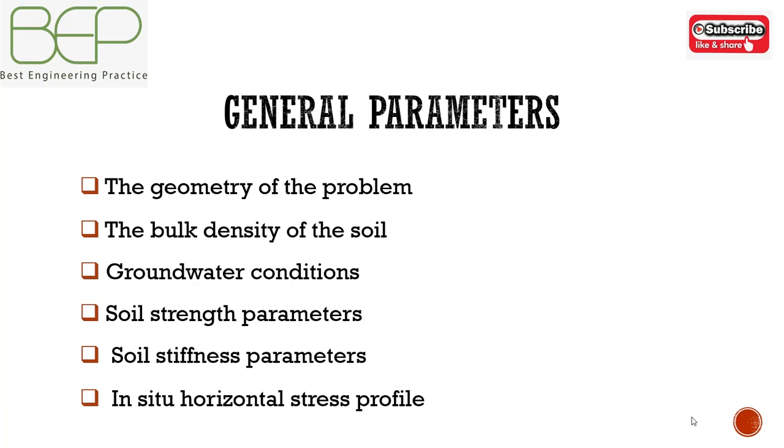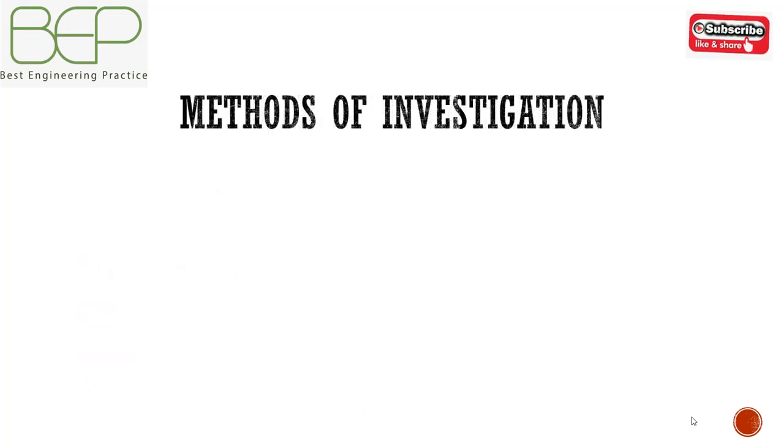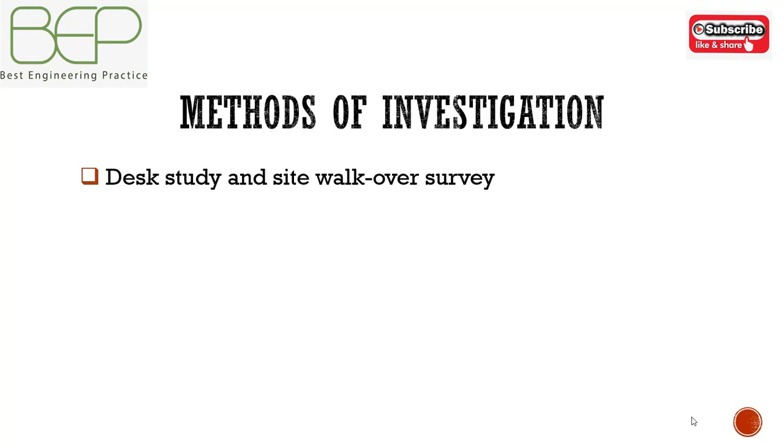The development of earth pressure behind a retaining structure is generally extremely complex. Therefore, even sophisticated analytical methods cannot approach the real situation, and all design is in effect semi-empirical or empirical. Soil investigation should at least consist of a desk study and site walkover survey, together with